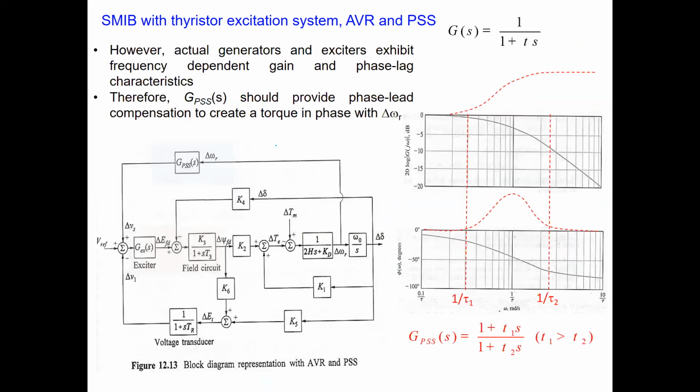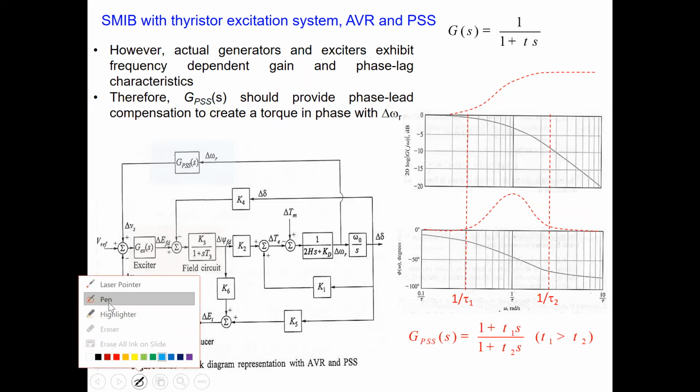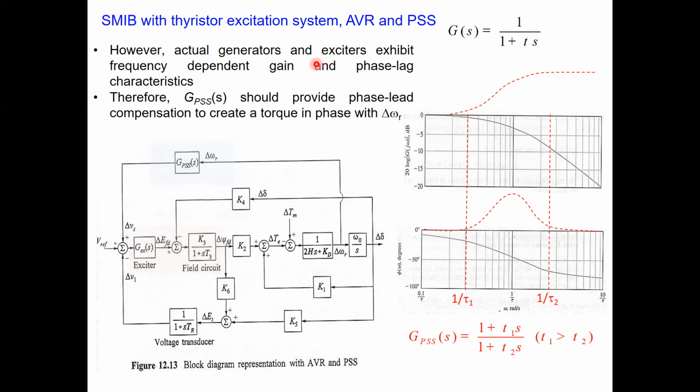Okay. So normally you have the generators, and then you have excitation systems. They always have a phase lag characteristic, and thus their representation is always in this form: 1 by something T. T is the time constant of this system here. It could be for a generator, it could be for an excitation system also, in the simplest form.